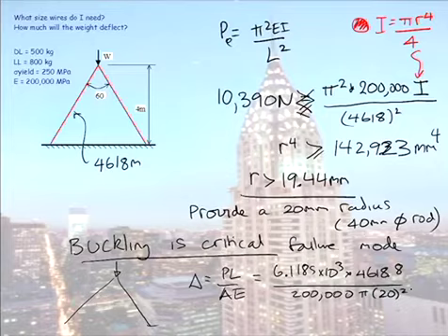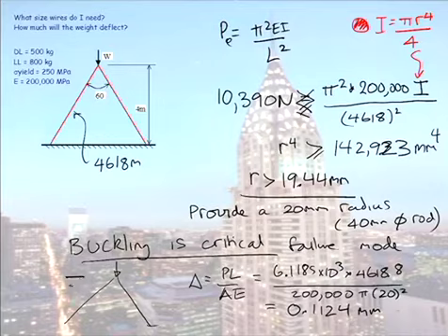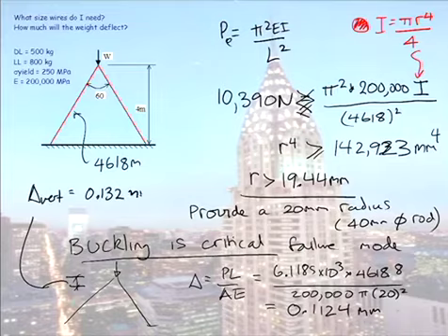Okay, so we're going to work out the deflection here. So this time round, is our cable going to stretch as much as it did before? No, our area is far greater. So our cable, well, it's not stretching now, it's actually shortening by a very small number. And I'll leave you to use Pythagoras when you actually work out the vertical drop here. You get a very small value. So a very negligible small value here. So you can work that one out yourself.